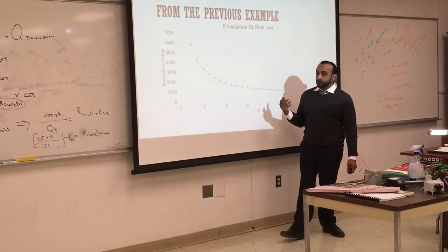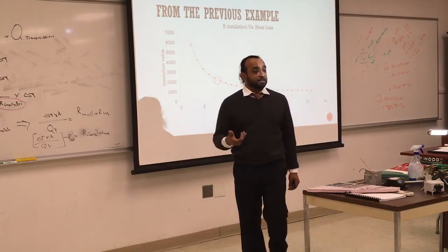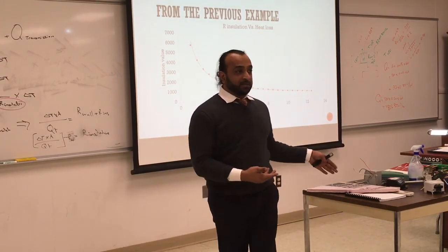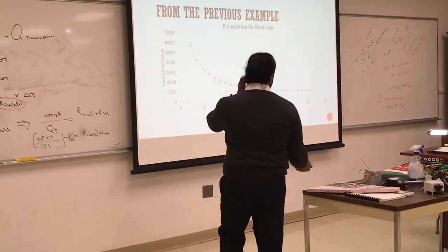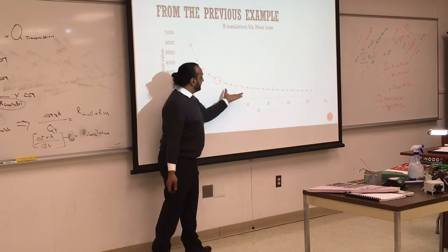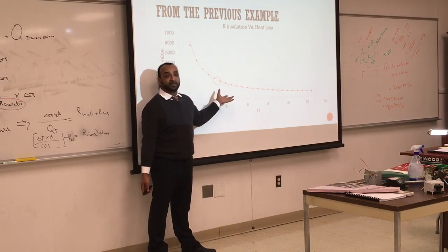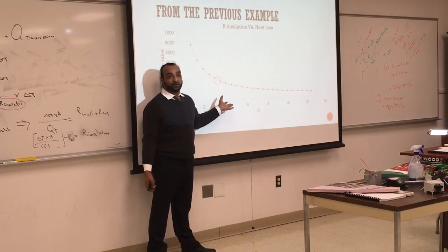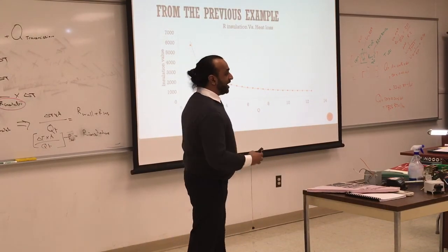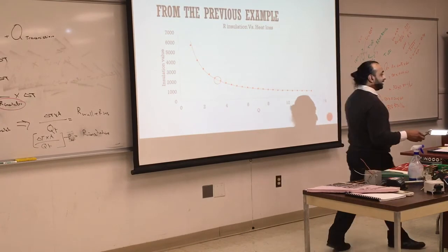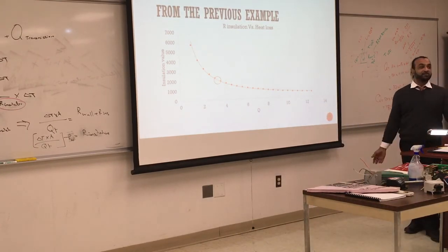And scientifically, the issue is at some point the conduction through the insulation becomes an issue. It's not going to reduce the heat loss anymore. So you're going to find a sweet spot where you don't break the bank and have some insulation. There is no way that you're not going to have any heat loss, but you need to have some kind of insulation. Did I convince you or not yet?